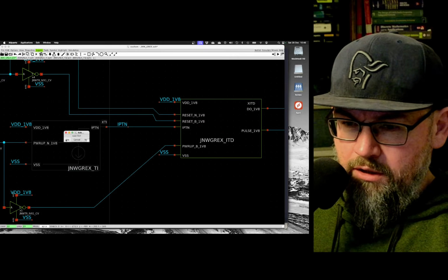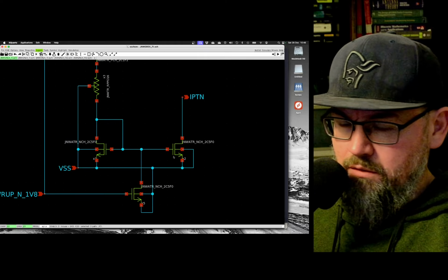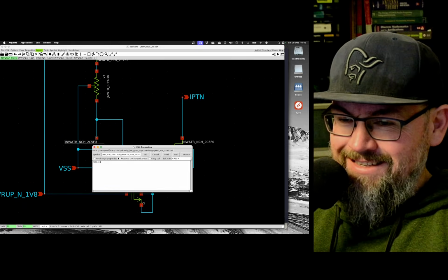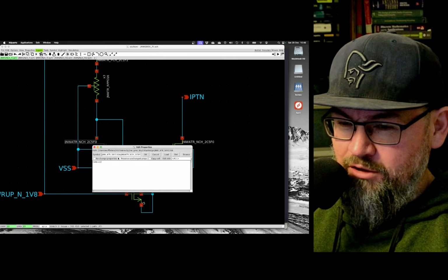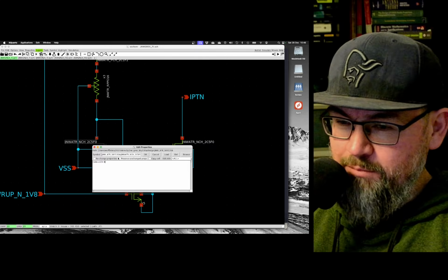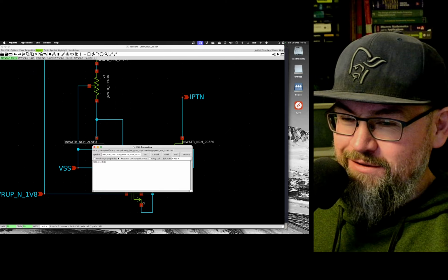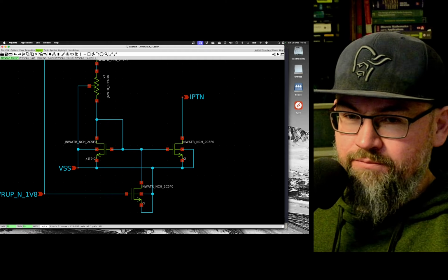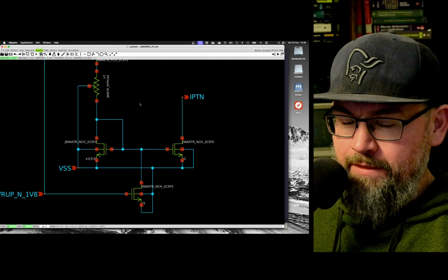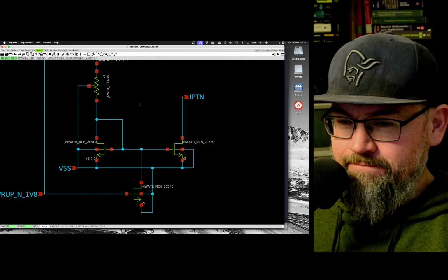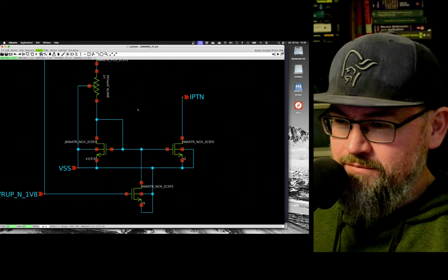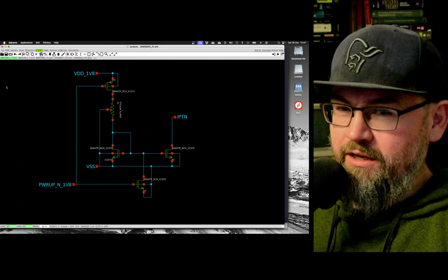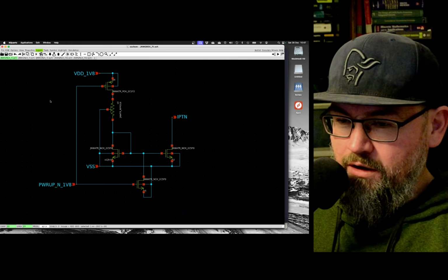And let's see, we kind of want to... Oh, I forgot one thing here. Here we should have... Yeah, we're going to place it. It's going to be a subthreshold. Okay, fine. Let's make a subthreshold mirror then. So that's 9,0. That's 10 devices, and that's 1. Okay. It's not ideal. It's a subthreshold current mirror. We should really make that cap much bigger, but fine.